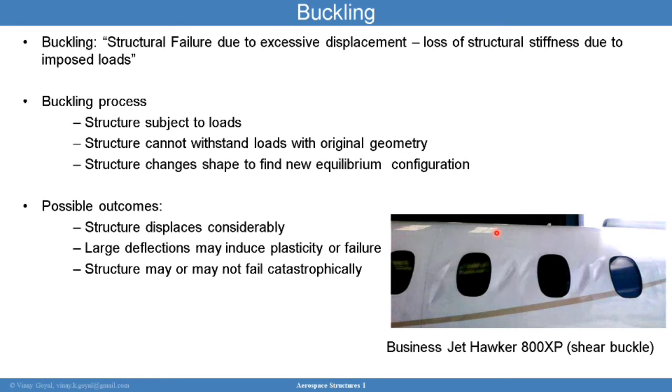You could also have buckling events that can degrade the capacity of our structural design, particularly cylinders in launch vehicle designs, and they're driven by imperfections in the shell. So any small imperfection in a thin shell can cause a significant degradation in strength, because that imperfection becomes a weak point, and so when loading is applied, that imperfection gets pronounced and it grows in size before actual buckling occurs.